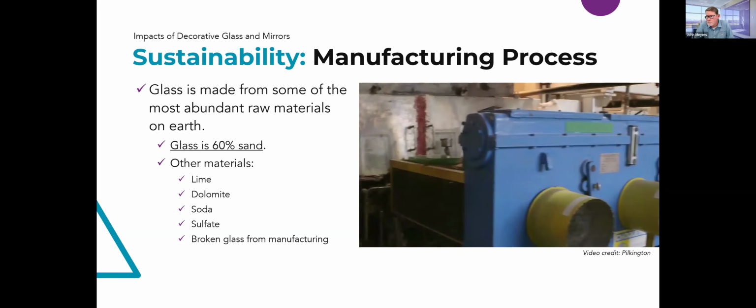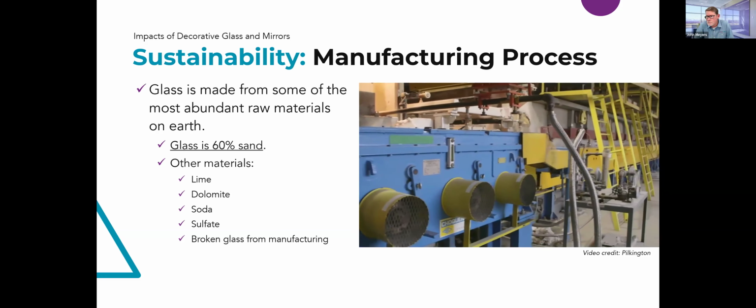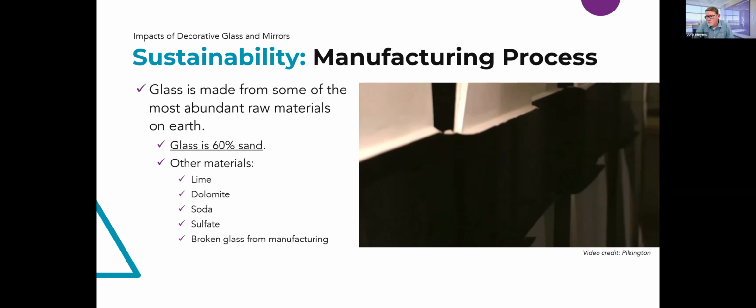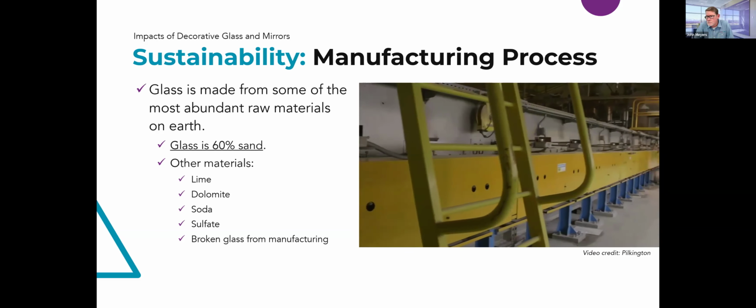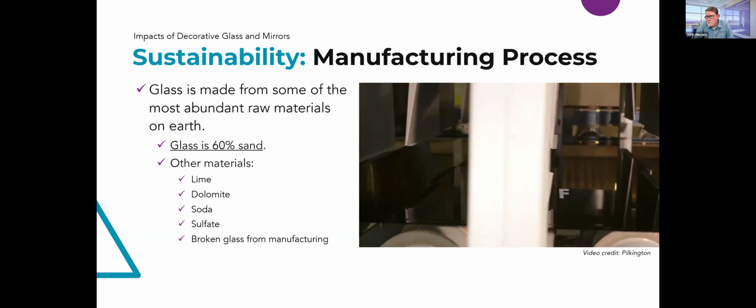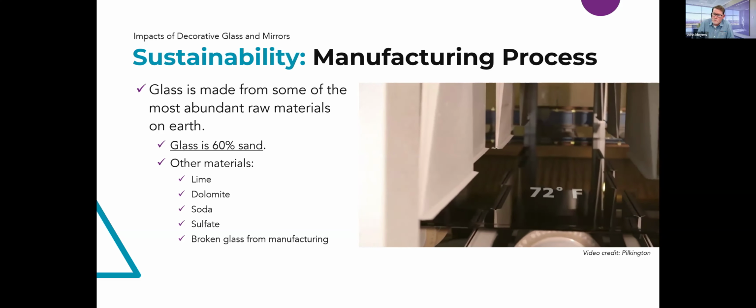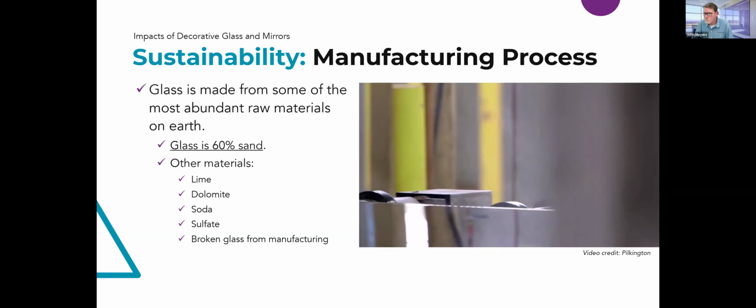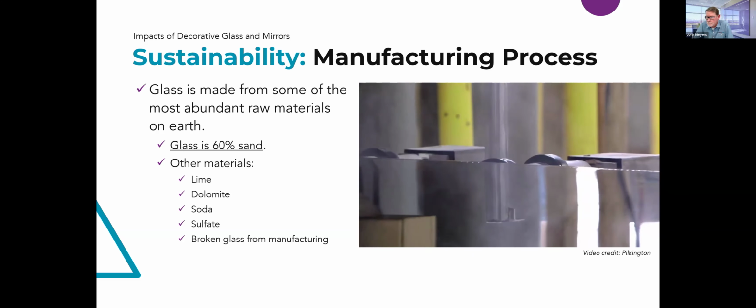The glass now enters the annealing layer, where any stresses are removed by a controlled cooling process. In a length of over 800 feet, equivalent to 3 football fields, the glass is taken from 1100 degrees Fahrenheit down to room temperature. At this stage, the glass is perfect.